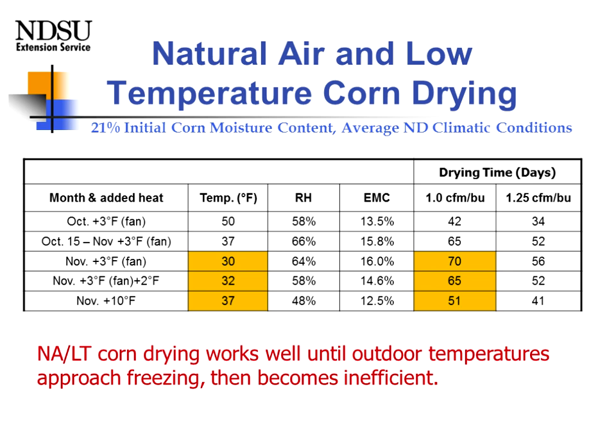So even in November, if we add 10 degrees of supplemental heat, we're dropping the corn moisture content down to 12.5%. Again, we're facing an over-drying charge, and we've speeded up the drying a little bit, but we could run the fan and the heater both for the entire month of November, when we have temperatures near freezing, and only get half of that bin dry.